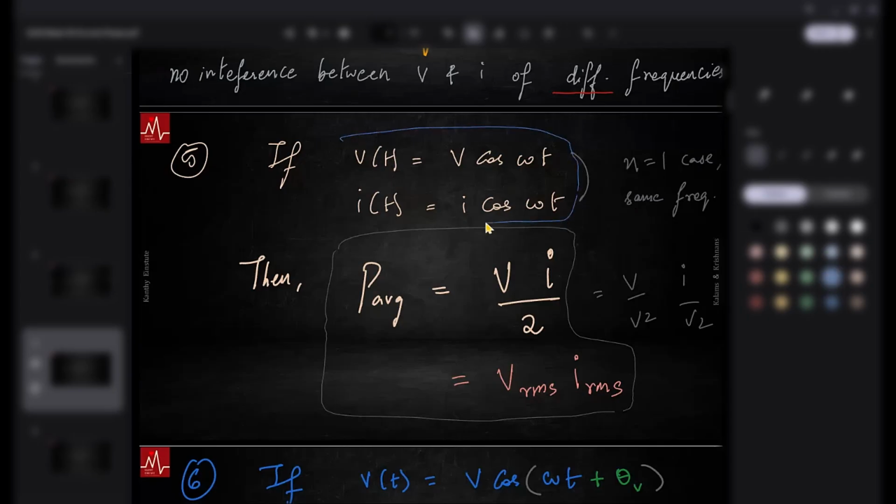Current and voltage will be in phase. Only a specific circuit is capable of doing this. It's purely resistive. If there is a capacitor and inductor, they cancel each other. Impedance is purely real. There is no imaginary part in the total impedance of the circuit. Yeah, that is very good.